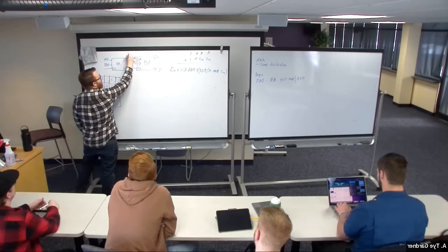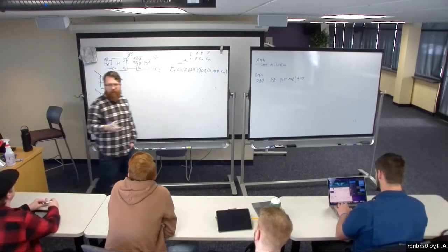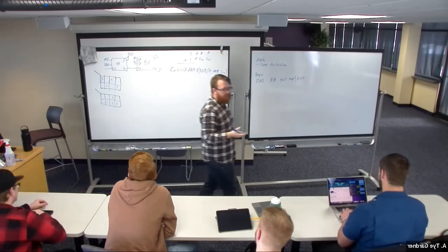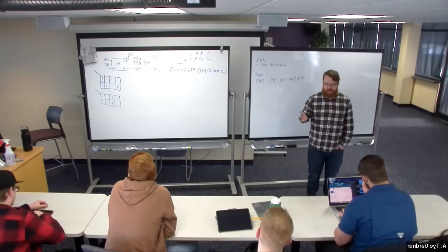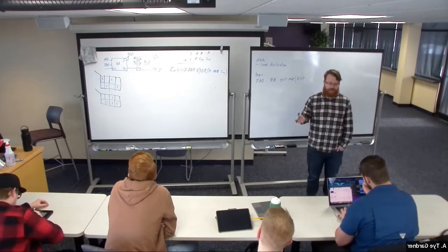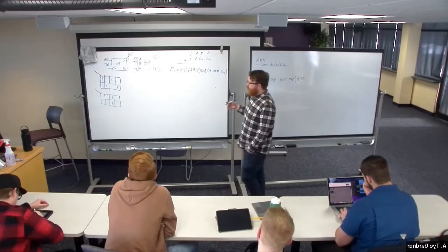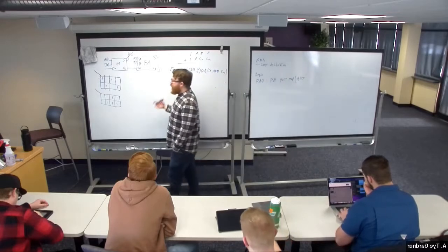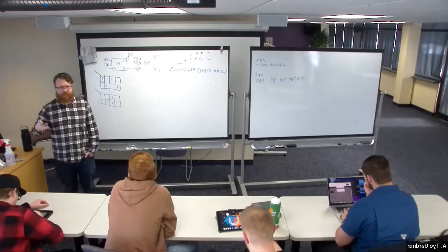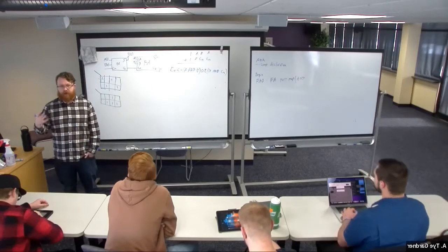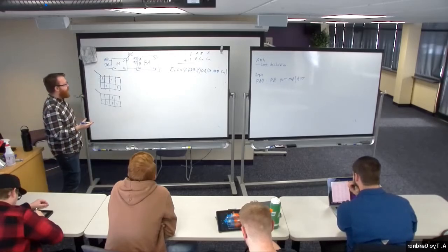This is going to be S at 0, right? The parentheses are saying that I've created a standard logic vector, which is just a vector of standard logic bits, right? It has more than one in it. And so what I'm going to do here is just walk through again, because having this rehashed is never a bad thing, because this is where people are still struggling to get. And once you understand this, you're pretty much good for a good chunk of the difficulties of the class.